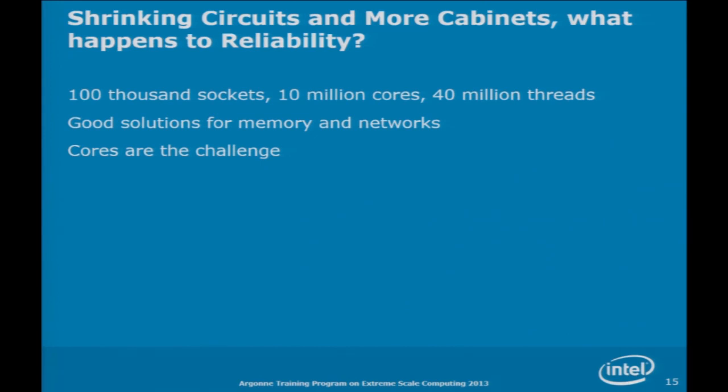But anyway, for memory chips, ECC works very well, and we have bigger ECC, so we can cover more bits. Networks also work well. The reason we're quite used to dealing with errors in networks is that we're pushing up the frequency right to the edge where you routinely have errors. And we learn to live with it by having link-level retries. When we get an error, we just retransmit the same packet, and chances are the next time it just goes through. That's routine and acceptable. It doesn't affect the program, and it's invisible to the application.